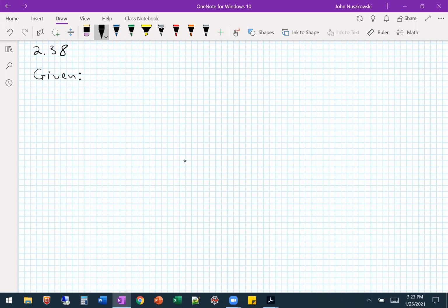Passage of an electric current through a long conducting rod of radius Ri and thermal conductivity K subscript R results in uniform volumetric heating at a rate of Q dot. The conducting rod is wrapped in an electrically non-conducting cladding material of outer radius Ro and thermal conductivity K subscript C, and convection cooling is provided by an adjoining fluid. For steady state conditions, write appropriate forms of the heat equations for the rod and cladding. Express appropriate boundary conditions for the solution of these equations.